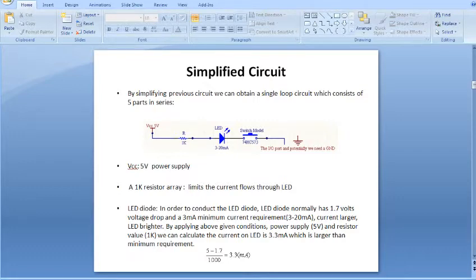If you go back to the basics of electronics, you should be able to see the characteristic between the voltage and the current of an LED. So that's the procedure we have to apply. Based on the voltage on the LED, use the voltage source minus that voltage drop and divide by the resistor. Because we can apply Ohm's law for a resistor, the voltage and the current are linear. Okay, that's the calculation.